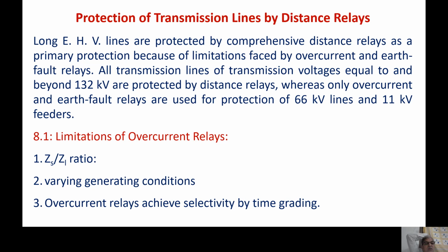Whereas distance protection does not achieve selectivity by time grading, it achieves selectivity by a different principle. We are protecting the line section by 3 different zones, and therefore the problem is quite a lot solved when I go to distance protection.